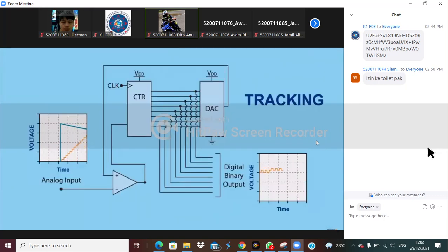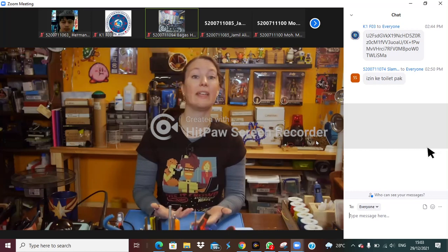The next type of ADC tracks the previous output signal, constantly comparing it to the analog input signal. Depending on if the input signal is less than or greater than it was previously, the counter adjusts up or down. This method is much faster since the counter never has to reset. The downside to this type of ADC is that it experiences a phenomenon informally known as bit bobble. Due to the fact that the output updates on every single clock pulse, the signal will always change at least slightly up or down.